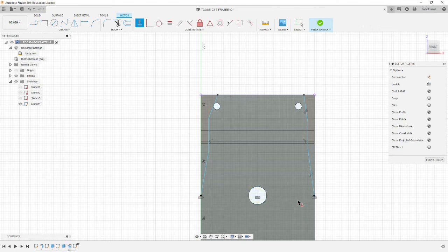So all of those are already set at their dimension and will stay horizontal at that location. Next, we're going to make the next angled points horizontally constrained, followed by the last ones. That way we only have to dimension one side, and those points will be constrained.